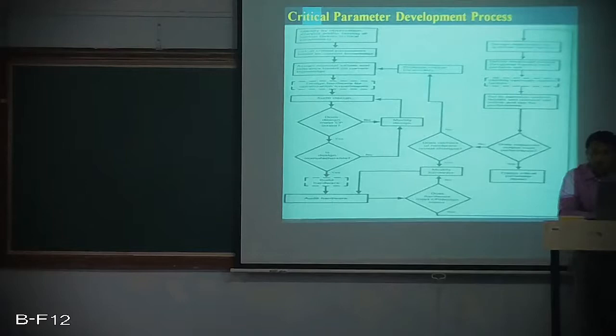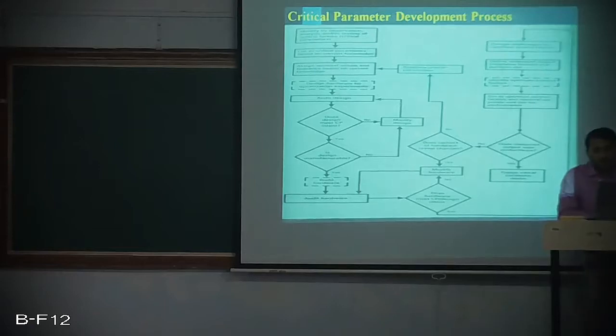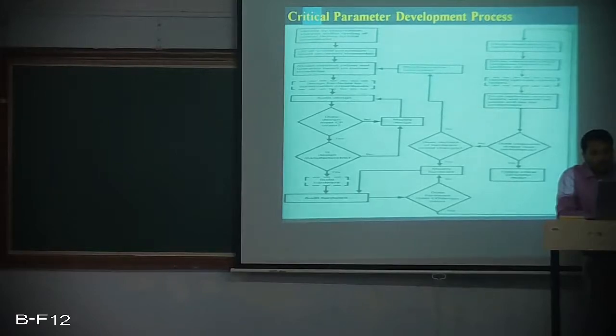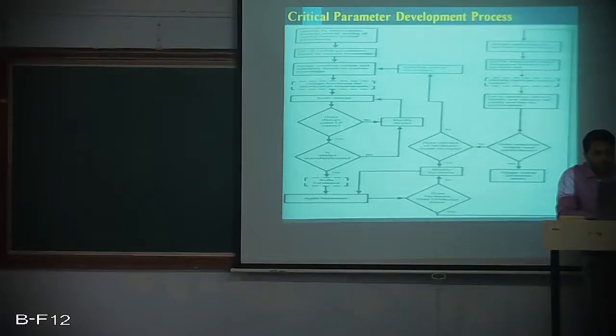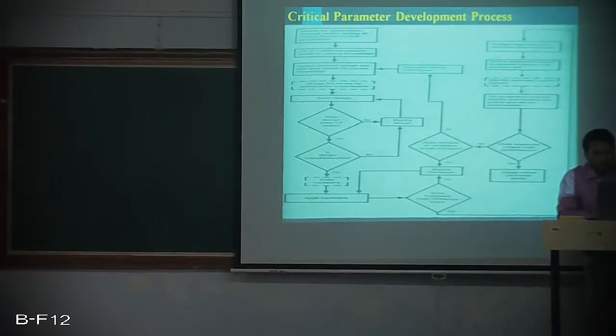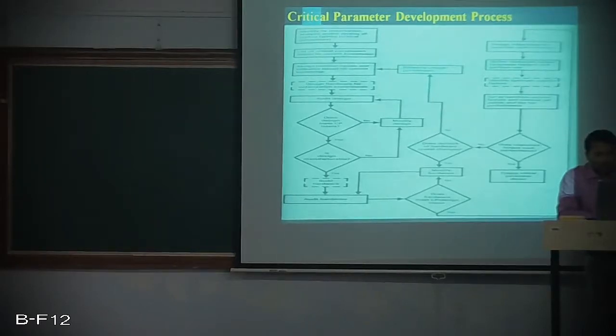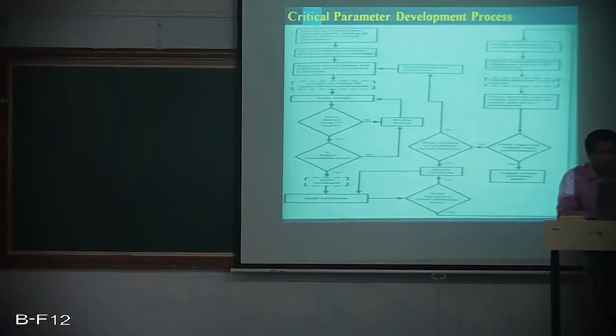What we are doing over here is basically optimizing the critical parameters, and then after optimizing we need to check whether the measured output meets the performance. If yes, then freeze the critical parameters design. If no, then recheck the hardware and review the designs, and if needed, modify the hardware, and then the process begins again with the audit of the hardware.